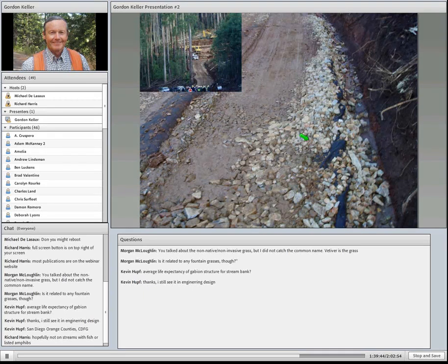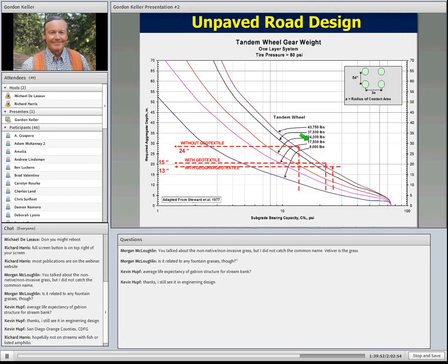So it's really a trade-off. Which is cheaper, the more rock or the rock plus the geosynthetic? And then there are very specific design procedures that have been developed, and I won't go into the details here, other than as a function of the soil type and the amount of traffic. Over on this side is how thick an aggregate you need. So in this example, without geosynthetics or geotextile, maybe you need 24 inches of aggregate for this amount of traffic and this soil bearing capacity here. If you do put down a geosynthetic, particularly for separation, you can get away with a little less aggregate.